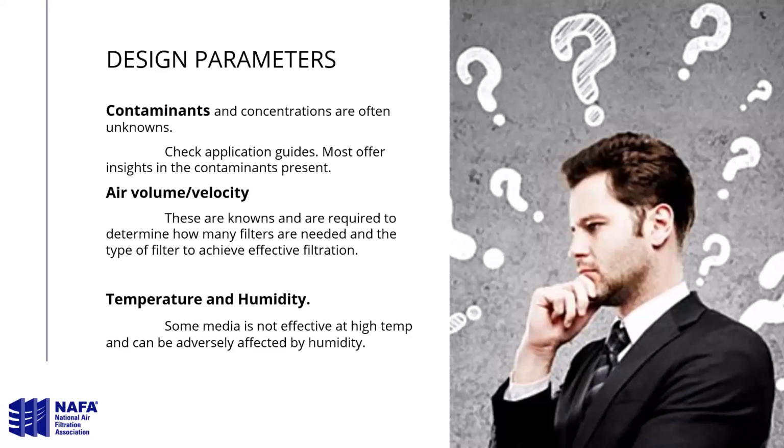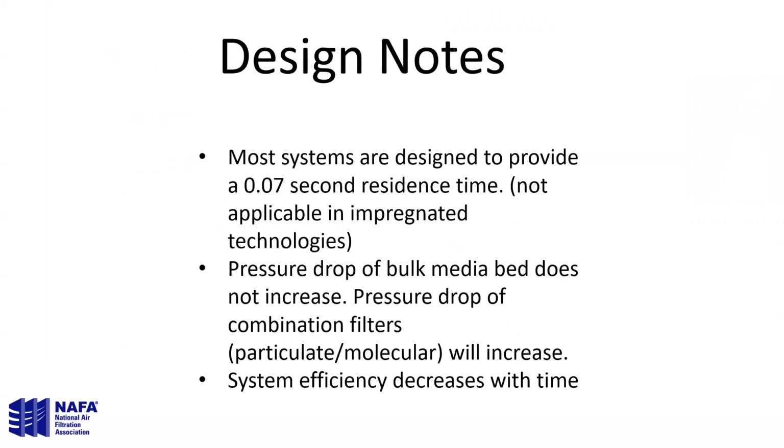And the velocity through it, well, that's beyond critical, because if you run it too fast, it will not pick up. Temperature and humidity, again, some media are not as effective at high temperature. Some can be adversely affected by humidity. These might be some of the things you want to know in case you want to blend the media. In most commercial applications, if your system is running and you're putting air through it constantly, humidity isn't a major issue unless you're living someplace like Florida, where real high humidity can last for a long period of time.